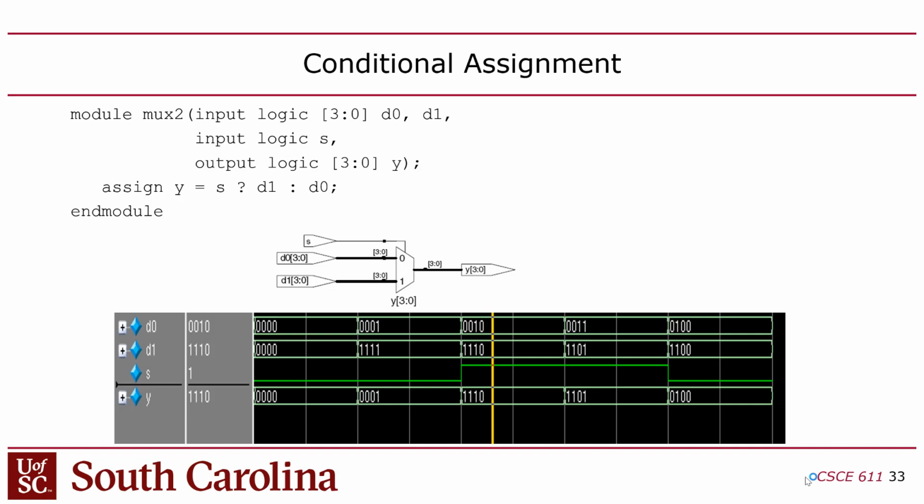So in our CPU, in the RISC-V instruction set, you can add two registers or add a register and an immediate. That decision, basically what goes into the second input on the ALU, is done through a mux, right? So you're going to have a lot of muxes in there, and muxes are done with ternary statements, so you have to be comfortable with putting these ternary statements in. Like I said, it's a very obscure feature of C, but a very common feature of Verilog.